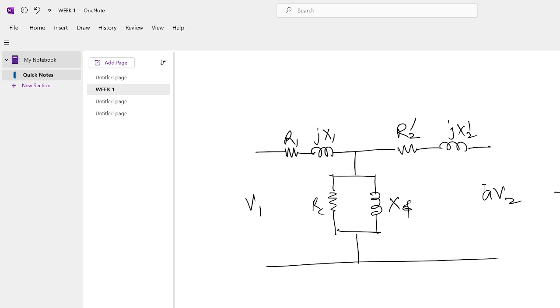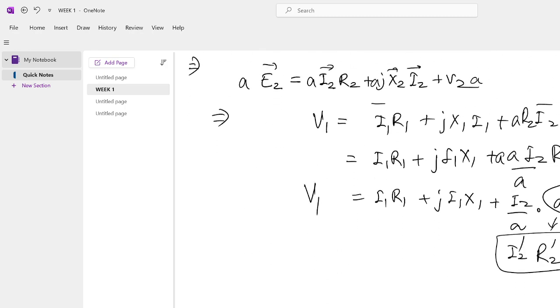Whenever someone asks about the rated value, that means at rated values, whatever is the nameplate detail, the rated power should be delivered at the rated voltage. If the machine is 500 kVA, it has to give 500 kVA at that specified 230 volt. Clear?